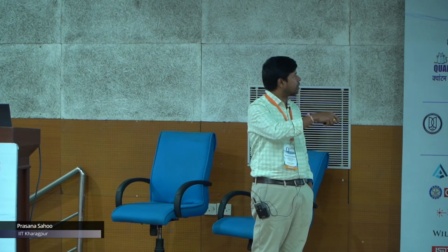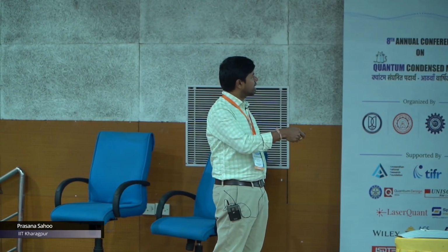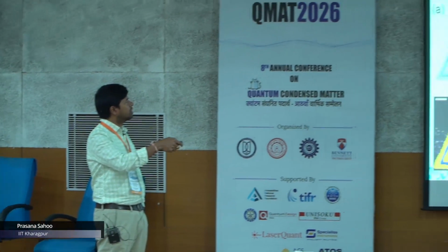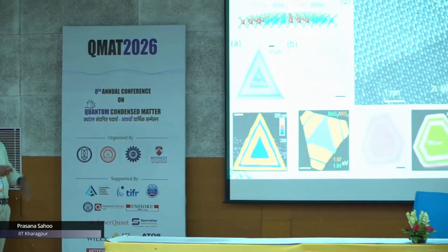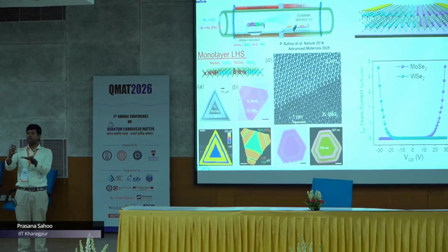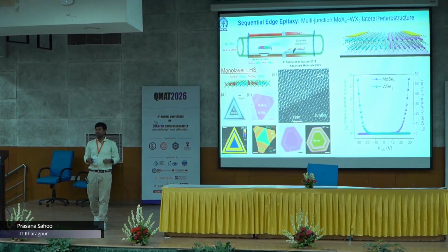You can see very well defined domains present at the lateral interfaces, and one can control monolayer, one can control bilayer precisely, and one can get an atomic interface of less than a nanometer. So we can go up to a sub-nanometer resolved interface, which is not accessible in 3D semiconductors. So we can see that well-defined structures can grow, and from a device point of view, one can make, suppose, MoS2 to WSe2, contact electrodes, make an FET, and by applying a backgate field, one can locally populate. Since these are spatially separate, one can spatially modulate carriers in one domain precisely.